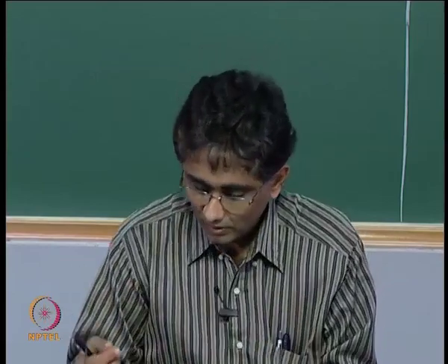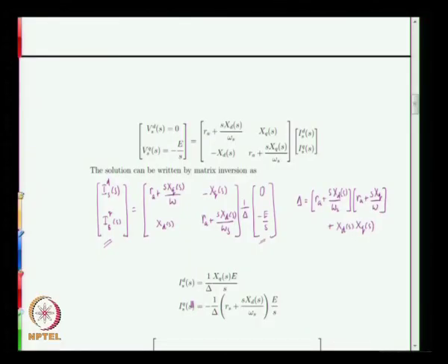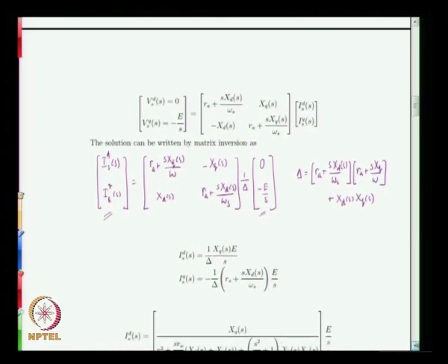After all, what we can measure on the stator side is the stator currents Ia, Ib and Ic with respect to time, and therefore we need to do an inverse Laplace transform, and before that we need to simplify these expressions so that they are in a more manageable form. So that involves lot of approximations based on what real life alternators are going to look like.